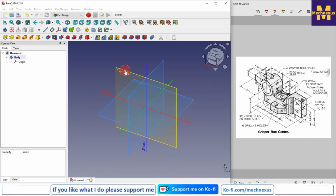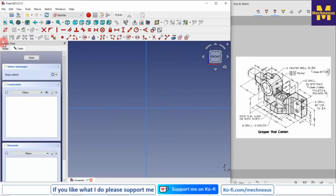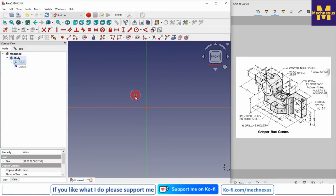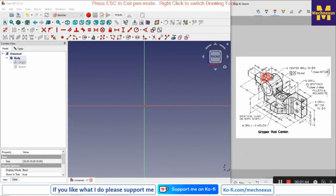So we will select this XZ plane and create a sketch, and I will turn off the origin plane. Now you are seeing here a blue tick on the sketch, so click on the recompute or refresh, or you can also press F5 from your keyboard. And now we will draw the profile, this profile. So let's start our sketching.